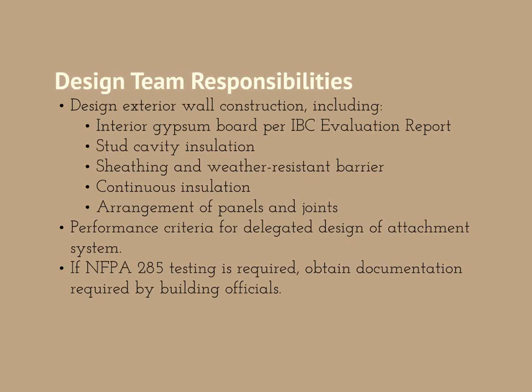Yep, there certainly are. So the design teams really got to take a look at this exterior wall construction, because it's more than just how you're hanging the ACM on the wall, but it's how you're dealing with the fact that you need continuous insulation, and are you having to interrupt that insulation to actually support the cladding. Many of the manufacturers out there are suggesting that the attachment system gets fastened back to Z-girts so that it has some continuous, substantial way of transferring the load back to the building, because if you're using compressible insulation, mineral fiber, for instance, you certainly can't put an attachment system over top of it.